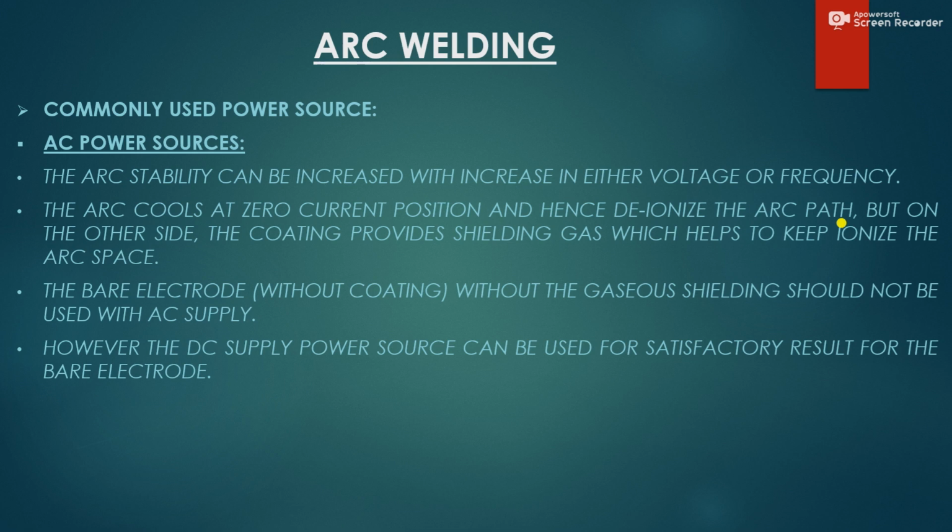So in that case, after the arc stabilizes or basically the arc cools down, that's when the coated electrode comes into action, where because of its coating there will be a proper gas shield around the weld pool which will prevent it from getting oxidized.